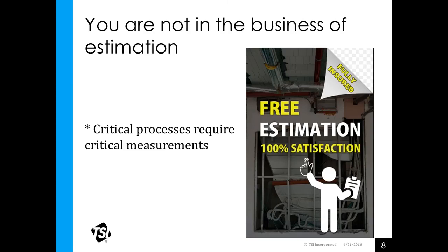For example, on the HVAC maintenance measurements, it's been lab proven time and time again to have potential to save a significant amount of energy. Any of the used measures have a significant potential for energy saving, both in residential and commercial HVAC systems. The first one being primarily airflow adjustment. So getting the first measurement in HVAC and critical HVAC, airflow, right pays big dividends.